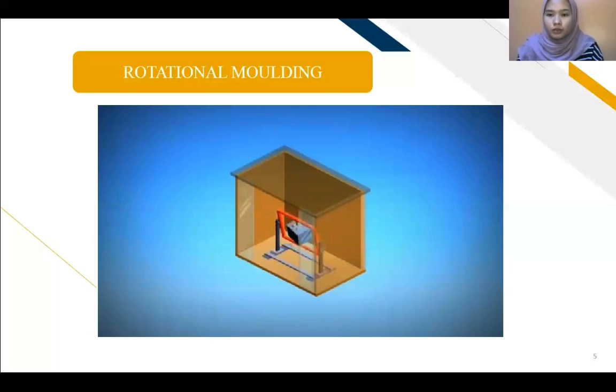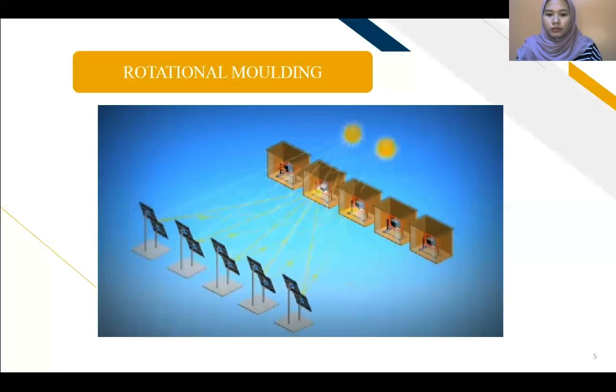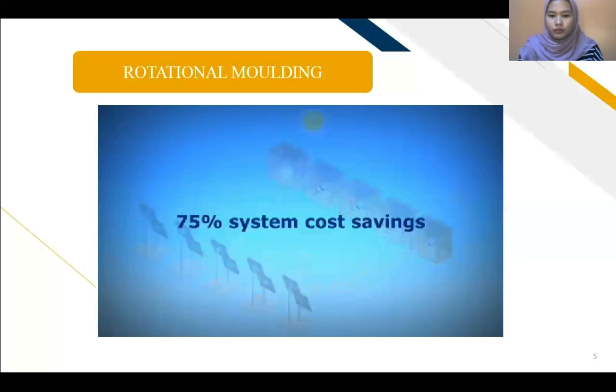Instead of moving molds in and out of the heat source as in traditional molding, solar rotational molding moves the heliostat beam from one inexpensive armature to another as needed. We replace costly machinery and fossil fuel energy with cheap, simple machinery and free solar thermal energy. Solar rotational molding systems cost only about 1/4 of what traditional molding systems do.